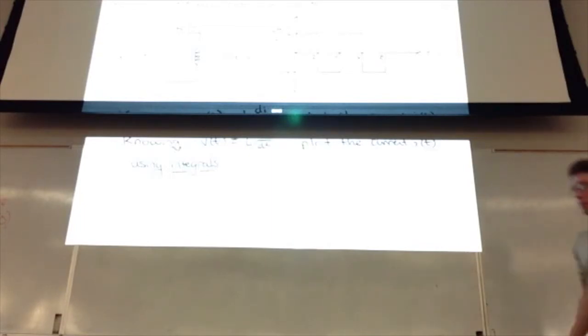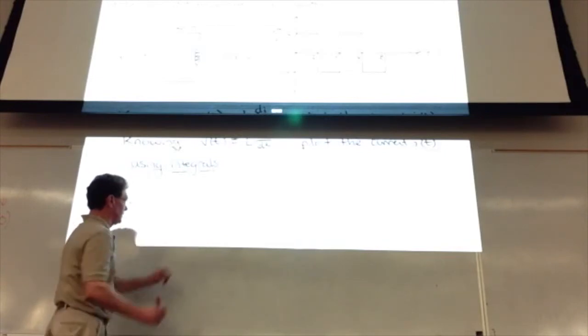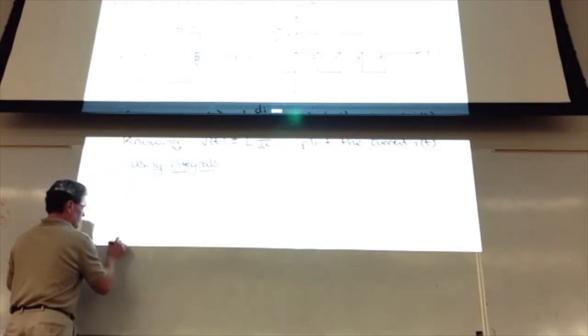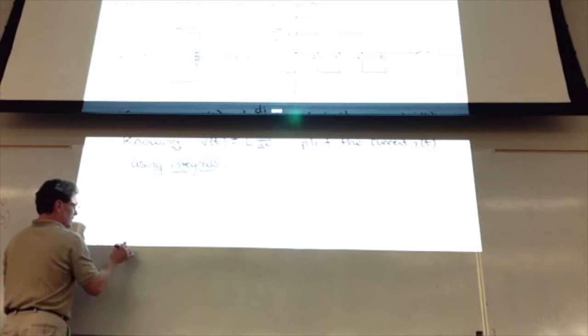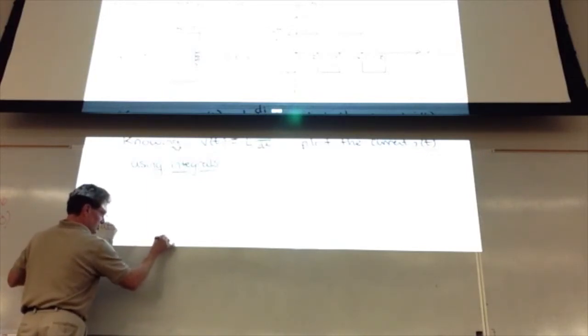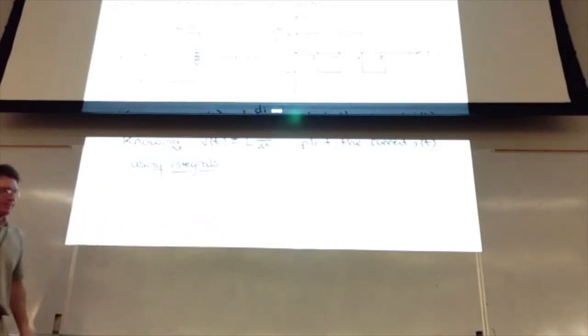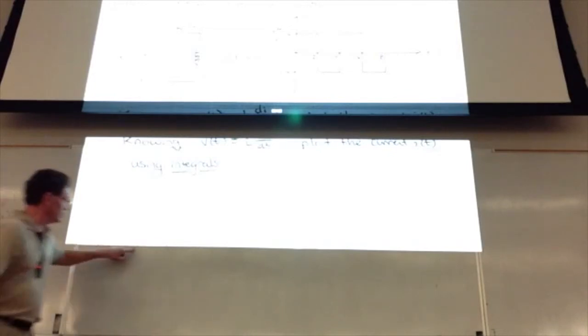That's what we're going to find: the current over those 4 time intervals. What's the integral of t? Oh, no, we have t here. So this is equal to 18 times t minus 0. Again, we're evaluating between the lower limit and the upper limit. So I of t for the first time interval is 18t.